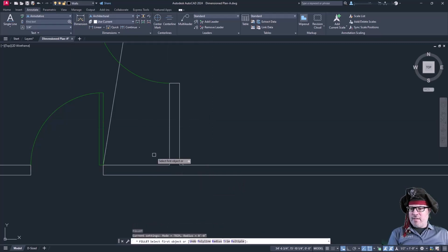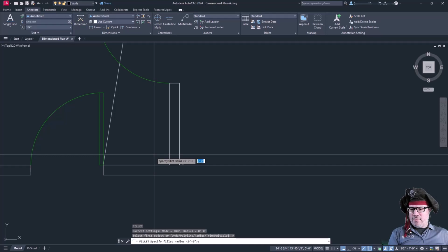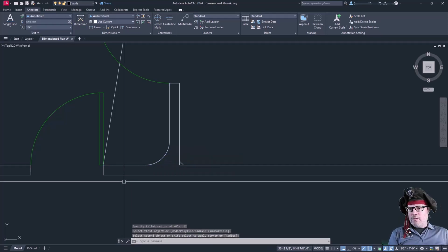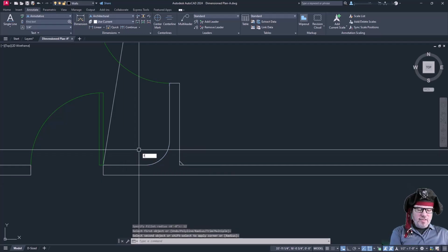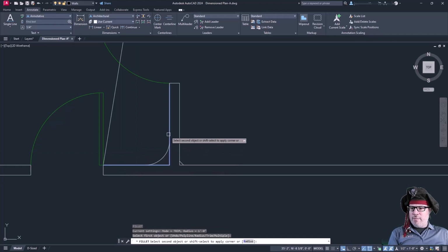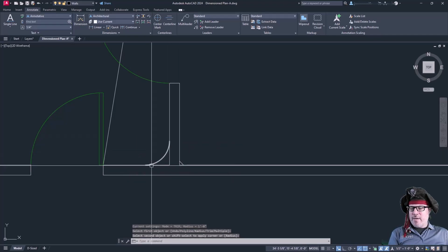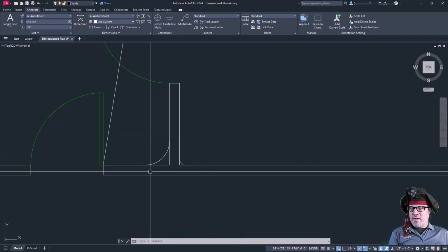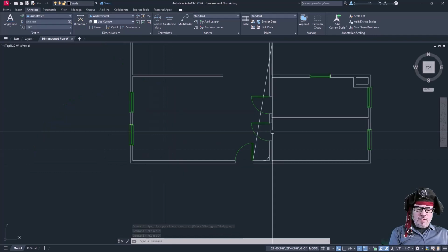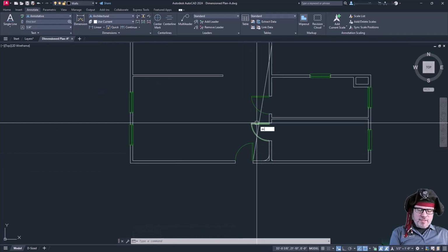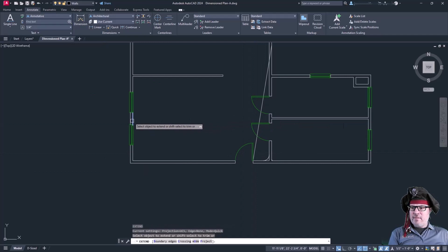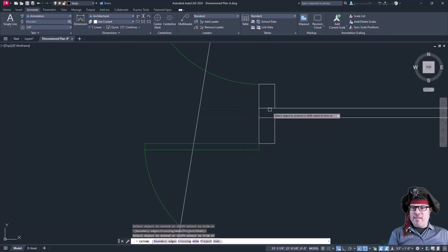Within the fillet command, set a radial distance and it fillets those elements together. Fillet again, hold down the Shift key, and it removes the radius, setting it back to a 0 radius, a vertex intersection or 90-degree angle. Within the trim or extend command, for instance if I'm in the extend command, I can extend objects indefinitely, or hold down the Shift key and it turns into the trim command without having to end the extend command at all.